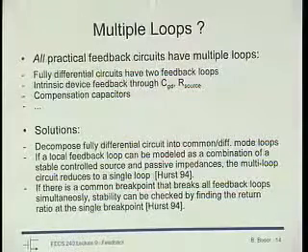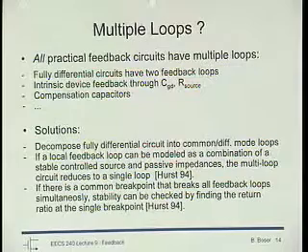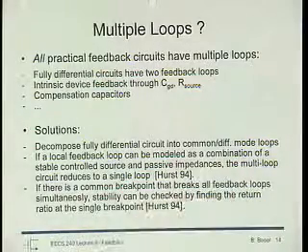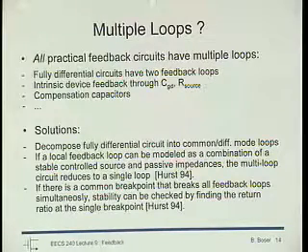And also the CGD feedback loop, of course, there we are totally out of luck, because we really cannot break that loop. The entire loop is inside the device, so we can't get at it. Fortunately, those smaller loops very often are stable, and then we can exploit something that is not always true, but in practice often true, and that is if every single block in a feedback loop is stable and the entire feedback loop is stable, well, then the whole thing is stable.